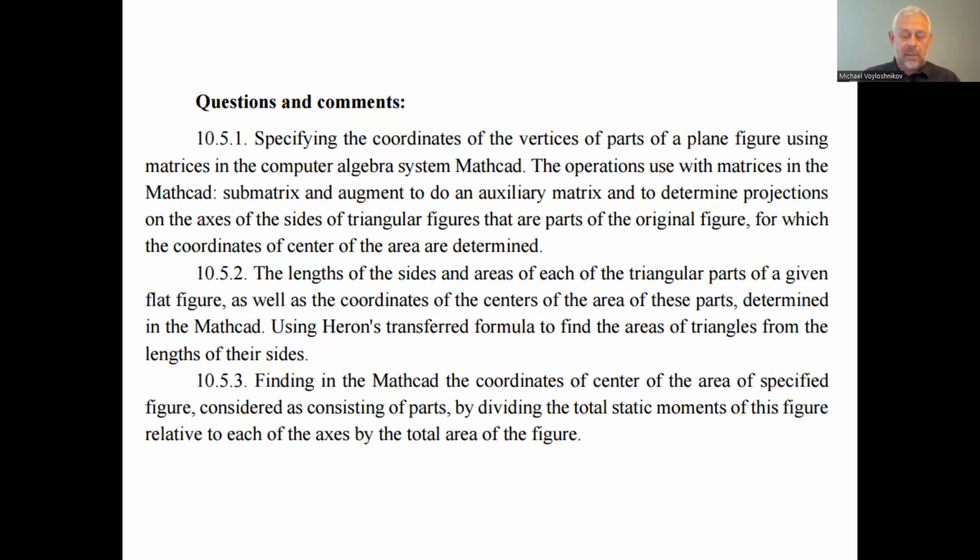So first of all, we have the assignment. If we have the assignment to find the area and the center of the area of a complex figure, a many-angular figure, it is relevant to subdivide this figure into a number of triangles. For example, because we have the standard formulas to find the area of triangles, maybe the Heron formula to find the area of triangles having the length of all three sides of each triangle. And besides, we have the formulas to find the location of the center of the area of the triangle.